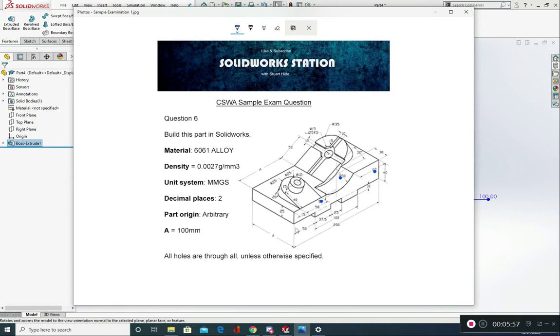And I'm going to do a check as well after this. So I'm going to put it in at 100, and then I'm just going to check that this point here, let's highlight that in a different color. Do that in red. I'm going to check that this point here is 60 millimeters away from that back edge. So that's the way that I'm going to go about this.